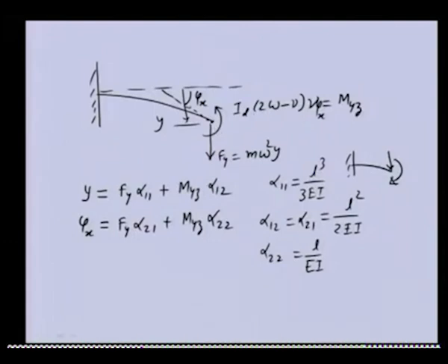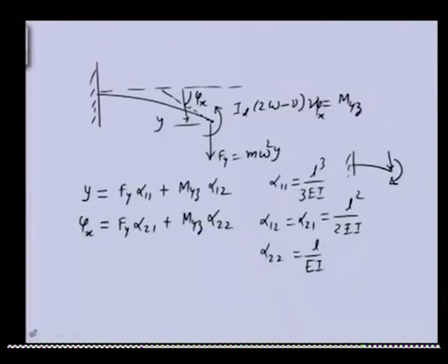So basically now we will be substituting this centrifugal force and this gyroscopic moment here, and we will be getting a homogeneous equation. So I am substituting the centrifugal force in this. In this particular case, if we go back here, this centrifugal force is due to the pure whirling case.